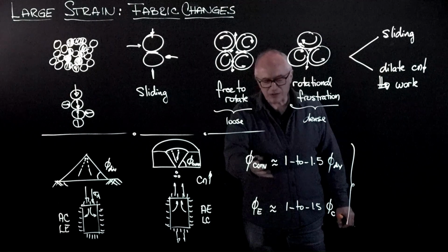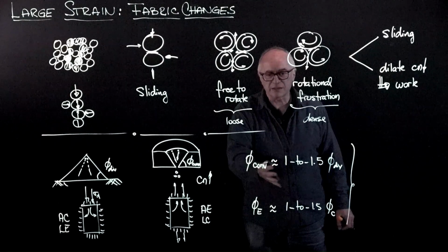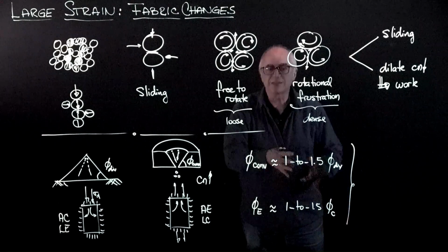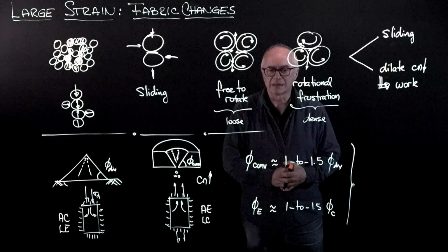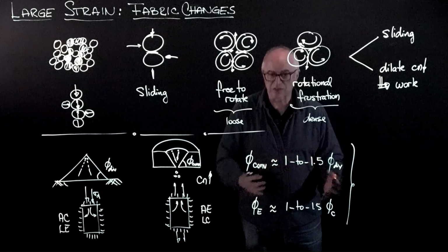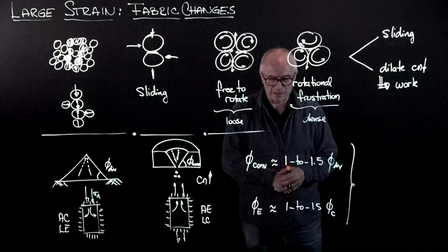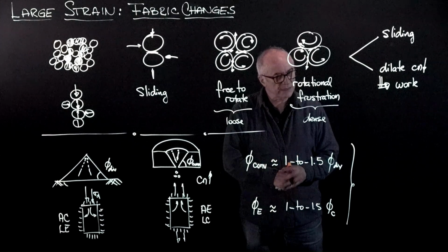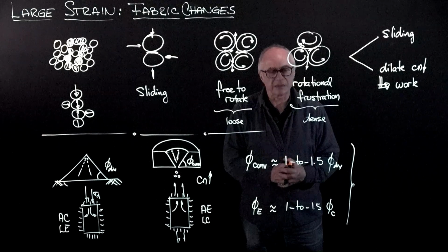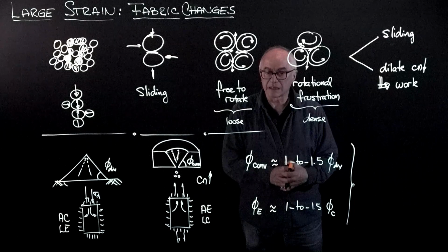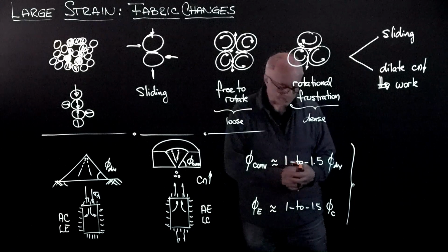The friction angle can change here from 33 degrees to 40 degrees. This is a huge effect, which has huge implications to stability analysis, to factor of safety computations. So keep in mind, friction angle anisotropy depends on the loading conditions.